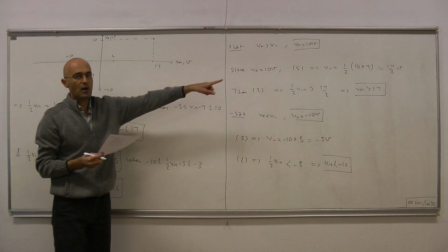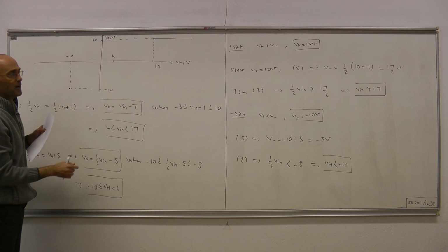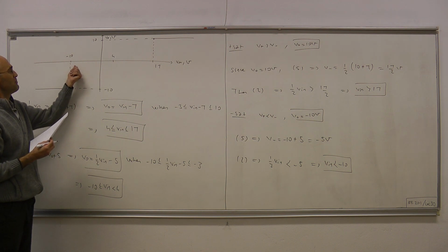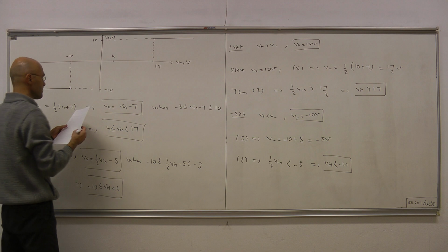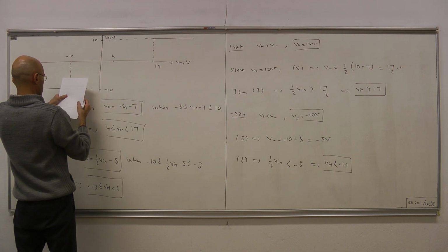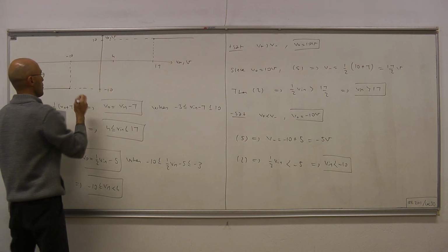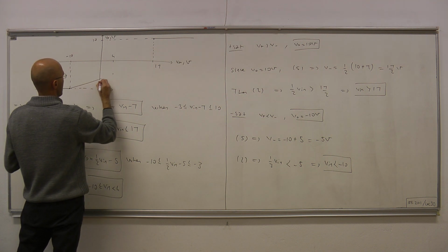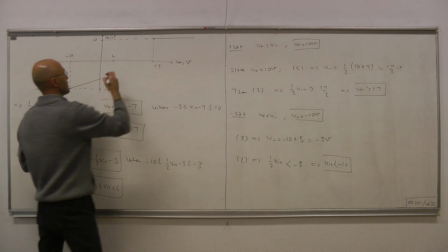So when V in is larger than 17, we're at positive saturation region. When V in is less than -10, we're at negative saturation region. And between -10 and 17, the op-amp is in linear region. Okay. So between -10 and 4, the slope is 1/2. Okay. Let's say, and between 4 and 17, the slope is 1.